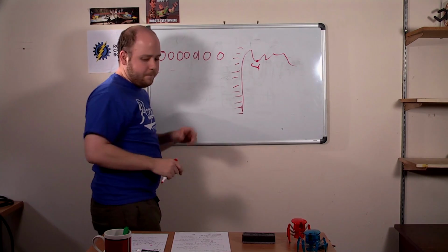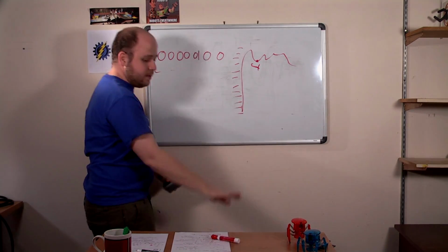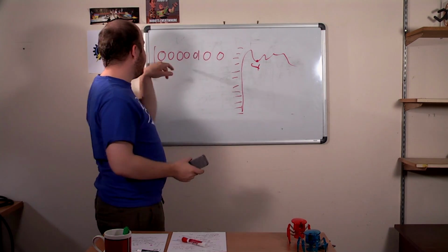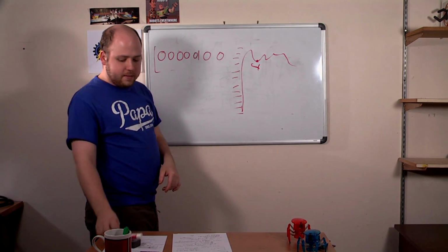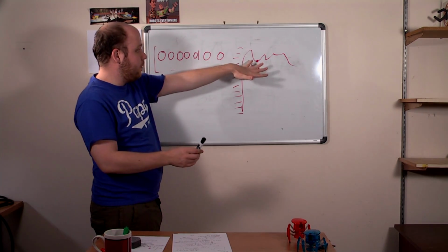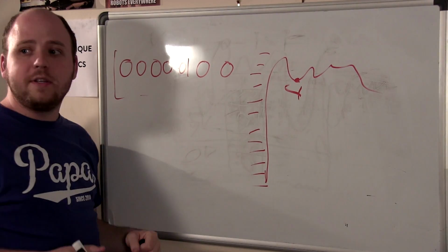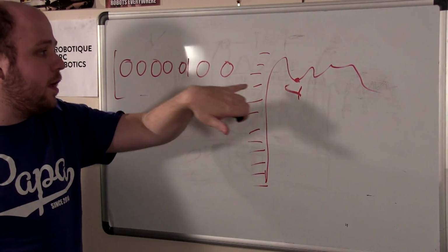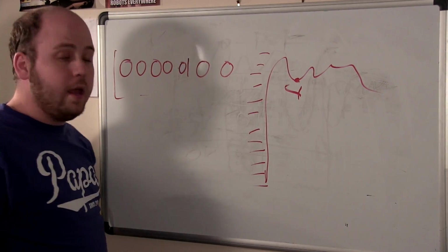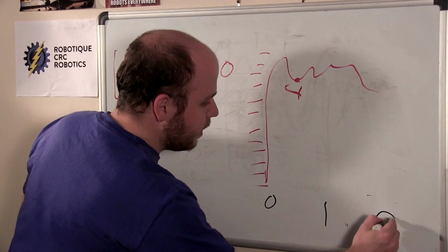So that's one thing. Then for each signal you send 8 bits. The second aspect is, once you got your signal value, the other important aspect is your sampling frequency, or how many data points you take for each step. So for example, let's say this is 0 second, 1 second, 2 seconds.